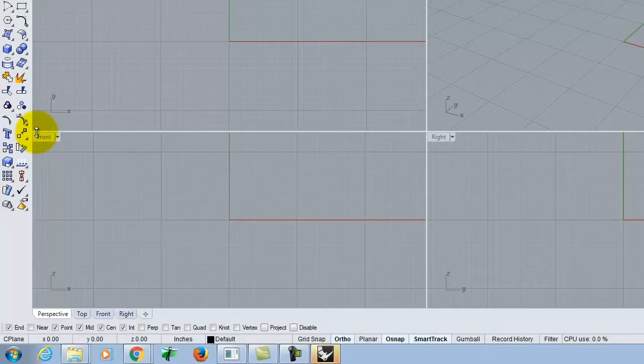We're going to model the fixture, the geometry, and the light bulb in a file, and then we're going to place that file into a scene, and in the scene we're going to assign V-Ray lights to it. Right? So the lights from V-Ray are actually invisible objects that do the light casting, and they're separate from the geometry of the light fixture. Right? And this will make a little bit more sense as we go forward a bit, and I show you how this works.